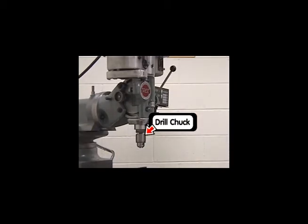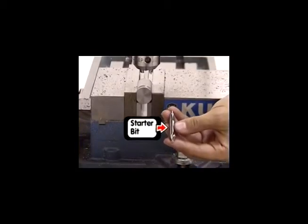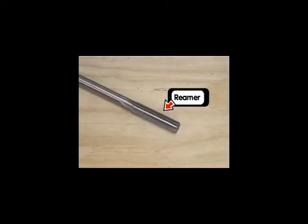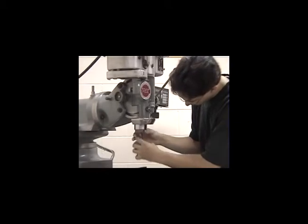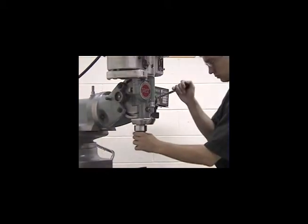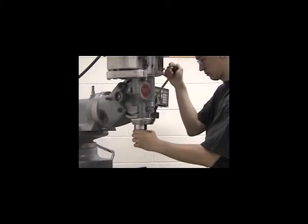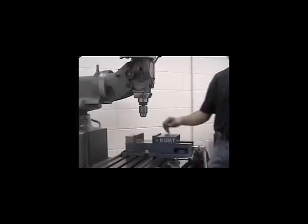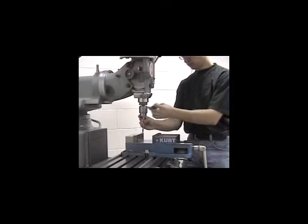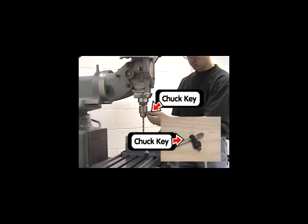The drill chuck, which holds drill bits, starter bits, and reamers, is attached to the quill with a collet in the same manner as an end mill. The drill chuck and drill bits are not strong in the lateral direction, so use them to make cuts in the Z direction only. Do not try to make X or Y direction cuts with them. A drill bit is placed in the drill chuck, and the drill chuck is tightened with a chuck key.